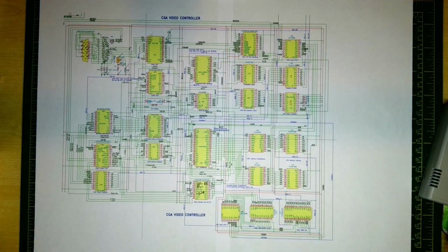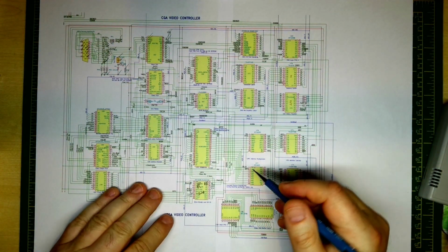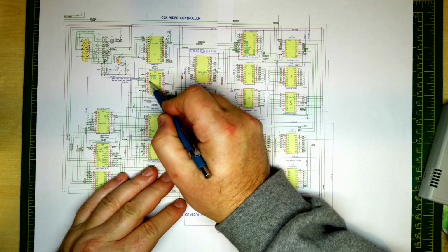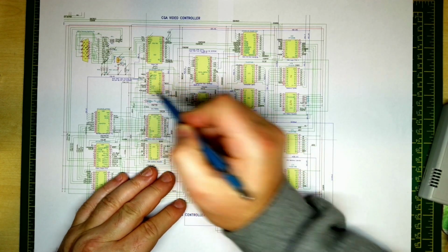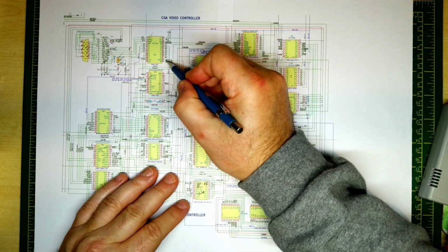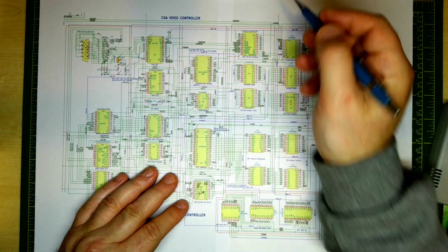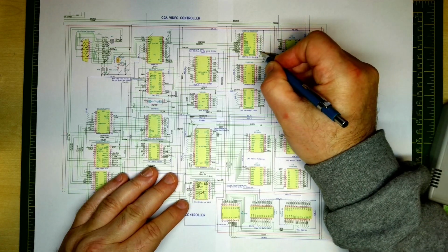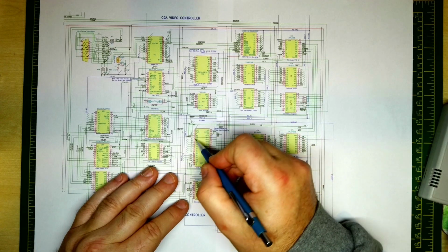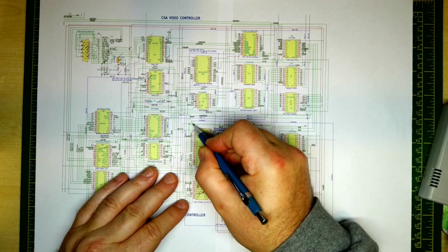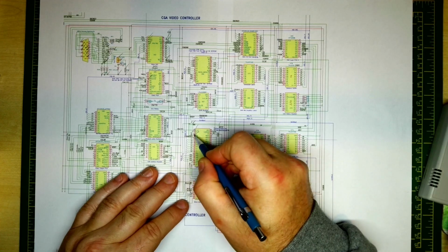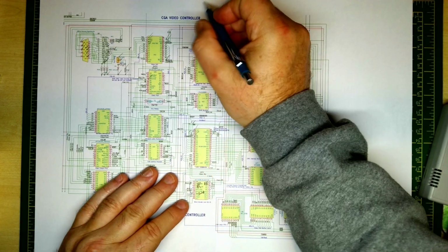I finished hooking that up, just going to check off things on the diagram. We've done the clock going all the way up to character clock up there. We've done display enable going up to there. We've got IO write, A0 and A1. We've got read write to IO write. Chip select. So we just need to remember about E.